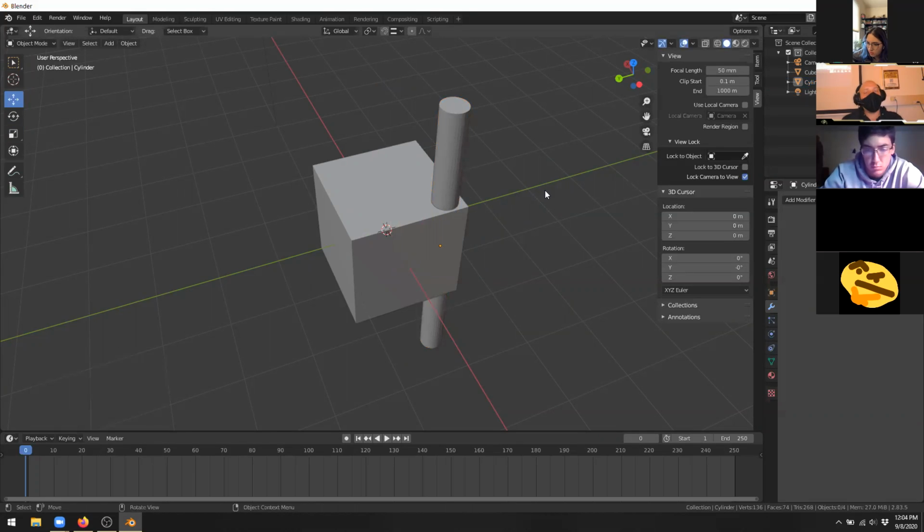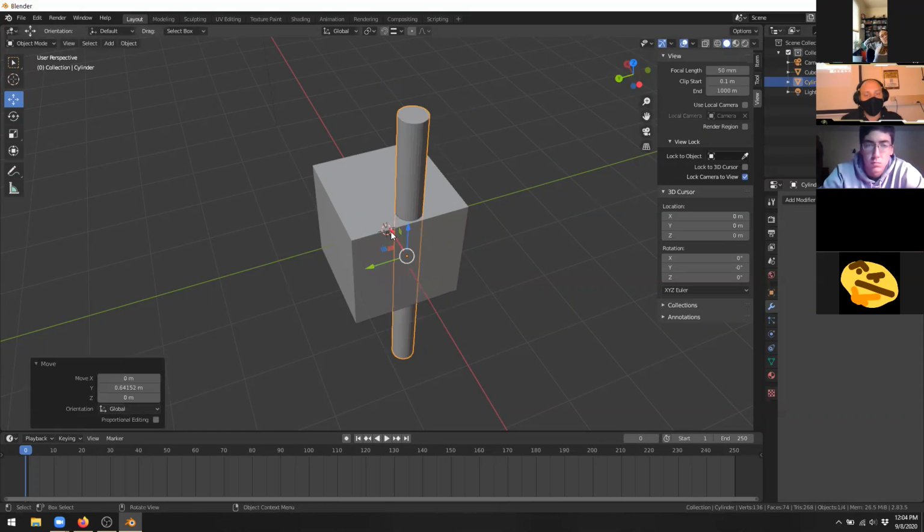And because it's still that same cylinder acting as a Boolean to the main object, as soon as I go in and hide the cylinder again, we can see the effect that has on our main object. So the hole's gotten smaller and it's moved to the side as opposed to where it was originally. Again, I can go the opposite direction of that.